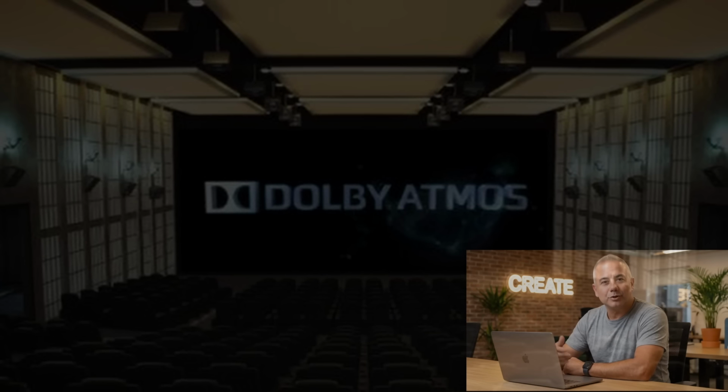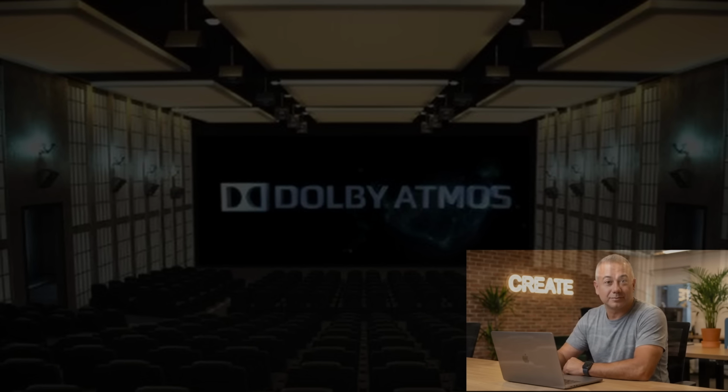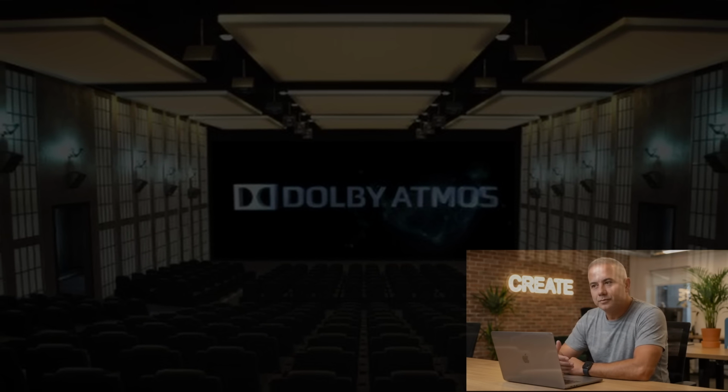Even if you jumped through all those hoops and mastered the workflow, there are two hidden acoustic traps baked right into home theater hardware that permanently corrupt your data. And until now, standard tools simply could not fix them. First, the Dolby volume offset. In commercial cinemas, top, middle, and side surround speakers are massive arrays, but at home, they are usually just a single pair. Because of this, Dolby embedded a permanent volume difference into these specific channels for home theater decoding. If you run standard sweeps, your measurements for those channels are inherently skewed.